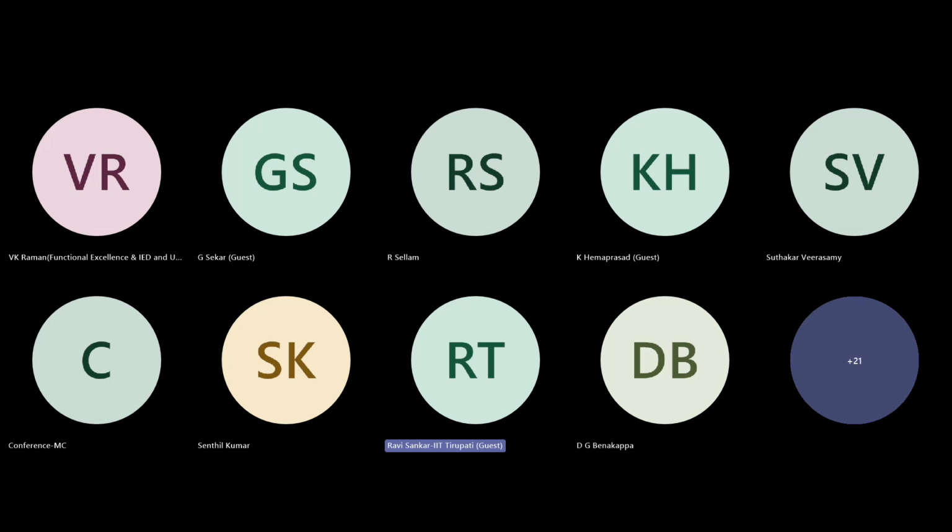So development of cutting fluid, development of the nozzles for the mist generation, and a lot of things. You require low viscous fluids again, because if the viscosity is very high, it cannot penetrate. So the capillary action is going to take place. How the cutting fluid will penetrate, how the tool wear can be minimized. Machining and machining fluids or cutting fluids play a crucial role to make the final product. So I pitched this one to IAF people. They positively responded, and looking at the scenario, I think we will definitely come up in a big way.